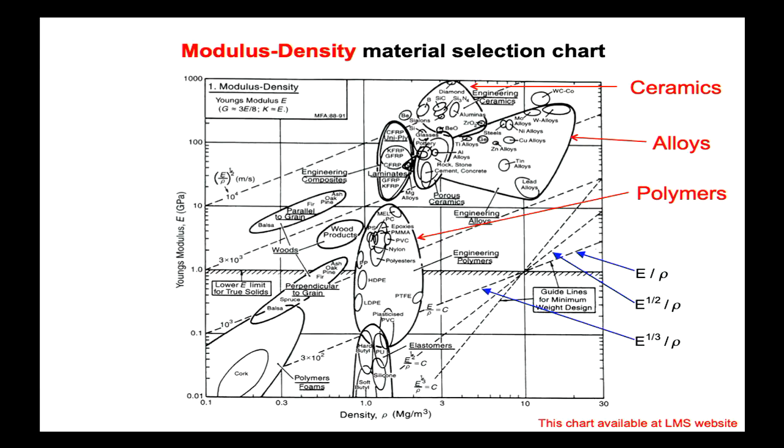And again, it might be easy for you all to think, oh, well, for any of these slopes it will be up around here or here or here. And I'd say, yes. That's why I'm always going to make it a bit more interesting, as is reality. It might be a material index with some additional constraints. For example, it must have a Young's modulus no less than the least steel Young's modulus. I could do that, and in a minute you'll see the example.